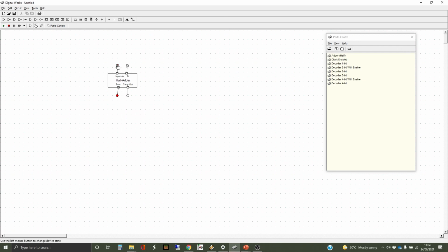And let's take the B input separately. That's exactly the same as it should be. And then I should have left that on. Put them both in. Sum goes down to 0, but carry out now is 1. And that is as we expected or as we wanted.